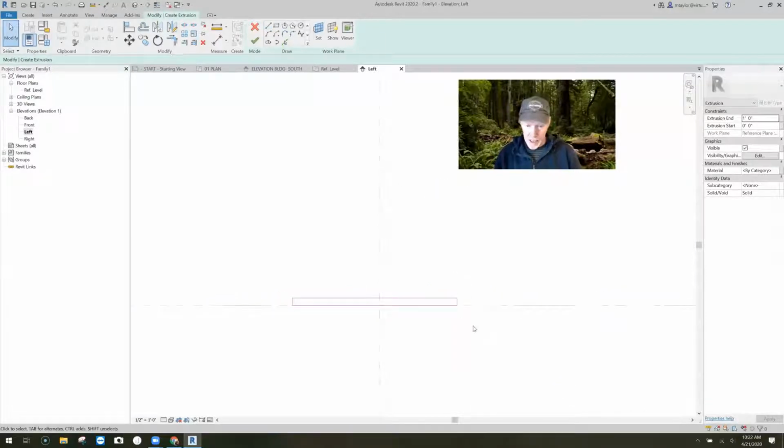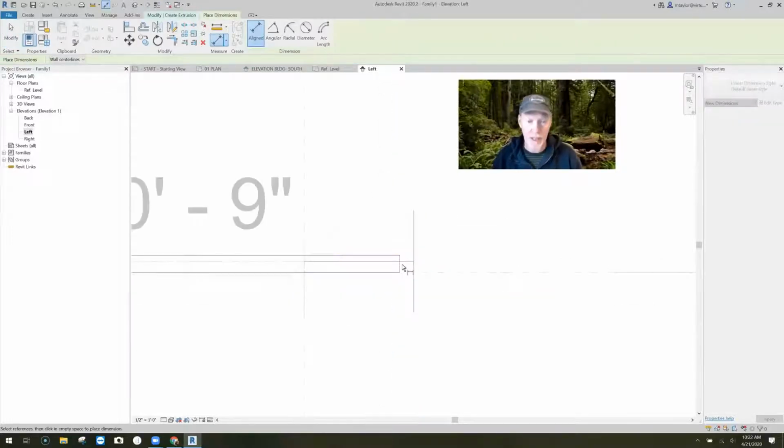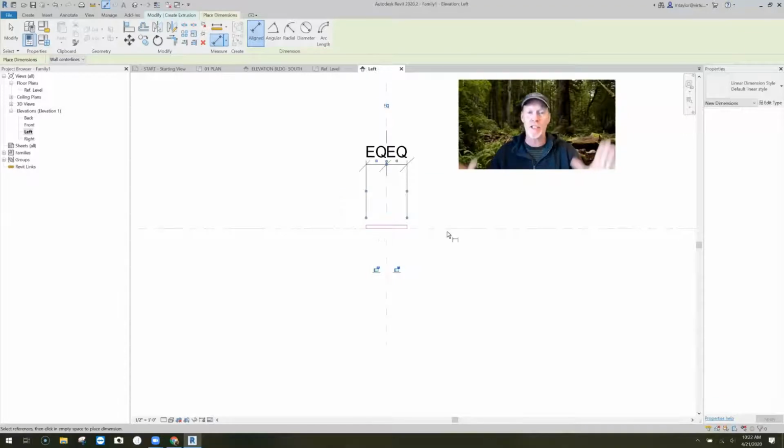Okay. Now this line over here on the right, it can be shorter. It's off center. See how that's off center? But watch, here's how you make things stay centered in Revit. You put a dimension on them. Let's say from the left side to the center and then over to the right side. And when you place that, you can click this equal. See, it's in equal, EQ through. It's in equal. But when I click that button, boom, it equalizes this so that it stays centered. Okay?